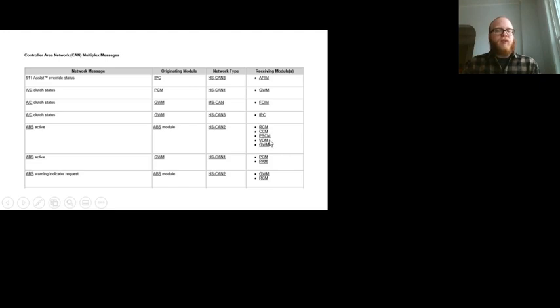The vehicle dynamics module goes along with some more of those accelerometers, the gateway modules at our data link connector, and I believe that this is our column control module, so this would be up at the steering wheel. Just a bunch of bits of information that they're picking up, doing their part to help inform the customer and also keep us pointed in the direction that we want to. That's probably what the cluster control module is for, is it knows which way we got the steering wheel pointed, and it knows from vehicle dynamics and restraints control what way the vehicle's actually going, and it's trying to line those two things up with each other.